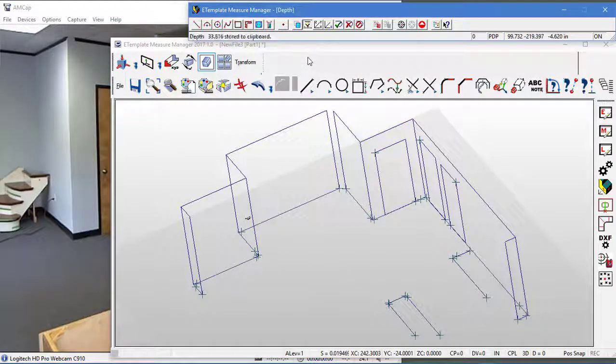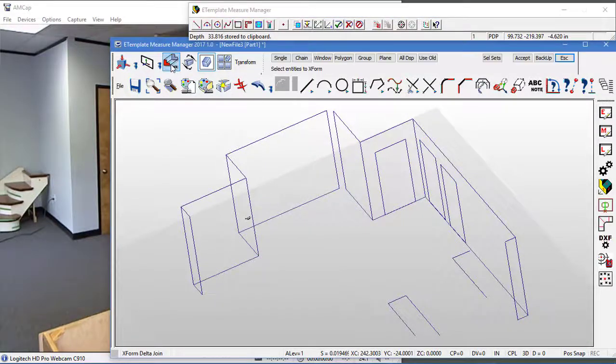There we go. Finally got it. Okay, so now I want to extrude again. Not all displayed. Window. I'm going to extrude this, plus that, plus this, plus that. I'll accept that. I want one copy. No changes to the X and Y. On the Z, I'm going to go up. These are 32s. I'm just going to put 32 in there and hit enter.